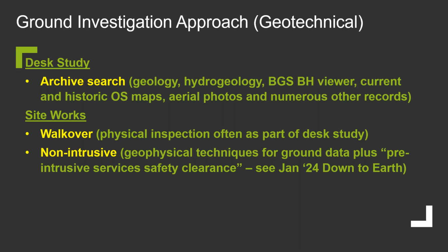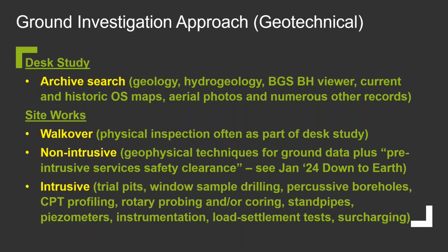There was a talk in January by Charlotte Usher on geophysical techniques, and some of those techniques are really, really useful with certain site geological conditions, so it's something just to be aware of, and it's one of the tools in our toolbox. And then we get to the intrusive stage where we're trying to get quality in situ data. We're looking at visual assessments, we're looking at large volumes of soil, we're looking at small discrete samples, we're doing sophisticated tests on those in the laboratory. We're trying to come up with our methodology for predicting what's going to happen on site. So all of that is taking place on every site investigation,